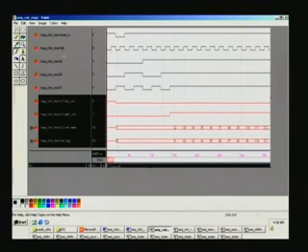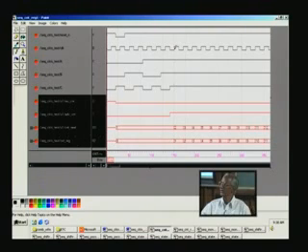ABC are in binary progression, being the inputs as such, and when ABC are 1 each, that is at this point, only then does the advance count go high, and hereafter once it goes high, only then does the counting start. Until then it was all 0 right up to this point, and the counter reg goes up by 1 only with the arrival of the next clock pulse, that is after advance count is activated. This is a combinational circuit as such, being a realization of ABC here, and we will just zoom it so that you can have a clear view of this.